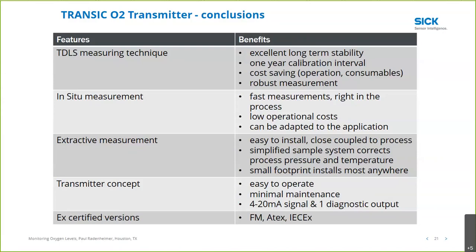Adding the PTFE filter, which I believe is something on the order of 300 microns, will give you about a 60-second T90 response time. So it depends on the speed of flow through your system. The higher the flow rate, the lower the T90 is.